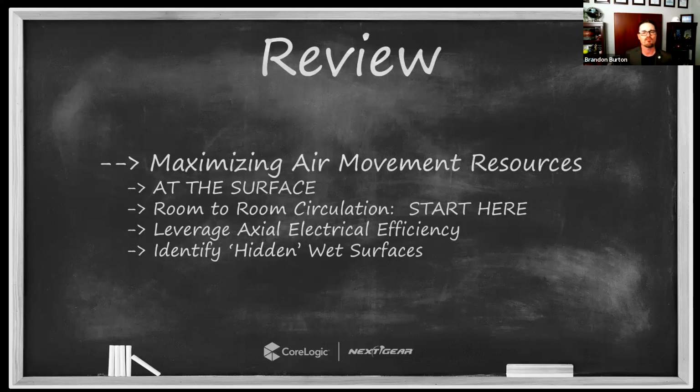So quick review, maximizing the air movement resource. Rule number 1, air movement must be at the surface. Okay, I can't stress this hard enough. I've made sure that in every one of our episodes to date, we've had an opportunity to throw this concept back out there. But if the air does not reach the wet evaporating surface, then the air is doing no work for you, right? It is the air in contact. I've heard it communicated as it's the air that communicates with the surface, right? It's in communication with the surface. And I like that phrase, but it has to be in contact. Measure for it, feel for it, validate it, document it, make sure that air is happening right at the surface.